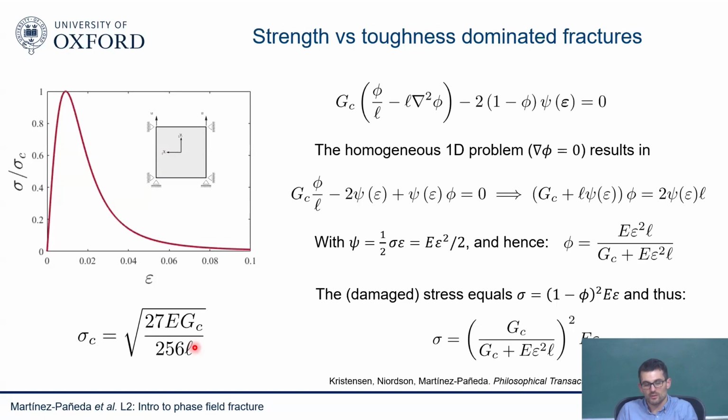That will give you the strength as well, basically. It will be connected to the strength. If you think of the strength, imagine that you have stresses ahead of your crack. Your stresses are going up. When do you start seeing macro cracking? Normally when your stress reaches some sort of critical strength, then you start seeing this macro cracking. So I think I get where you're going. There are other phase field models which are trying to decouple the length scale from the strength. Some of them are quite heavily applied to concrete, so we'll discuss them later on. It's more what we call the phase field cohesive model. I have a slide about those things.